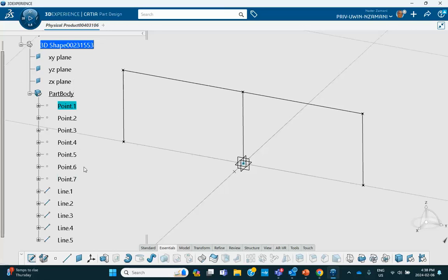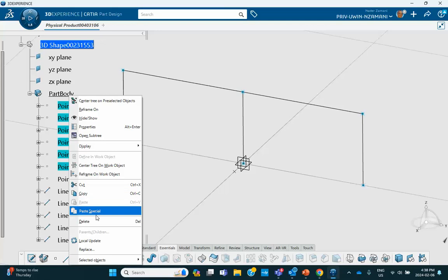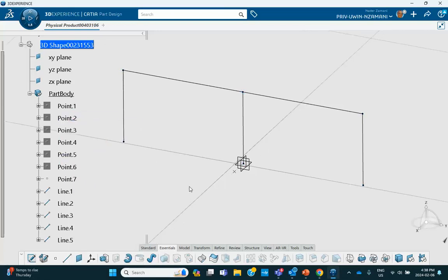Okay. Now these points that we created, we can hide them except for this last one that we're going to need at some point. I'll leave it there, but the rest of them I'm going to hide because I don't want to inadvertently put restraints or boundary conditions on these points or put loads on them. We don't have any loads, but you can't put them on points. Okay, so let's go ahead and apply material properties.